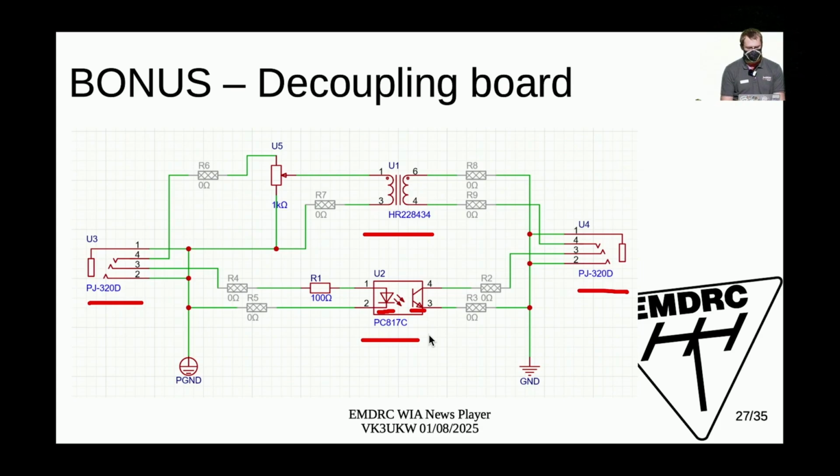In this case, they've probably got a transistor. All transistors are photosensitive, but in an optocoupler, you generally have a special infrared sensitive one. So whenever you put enough current on this side to light up the diode, your circuit closes on this side. It accomplishes essentially the same thing as a relay, just that instead of using magnetic coupling, you use light.